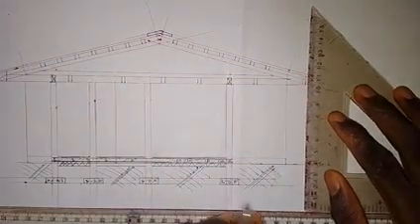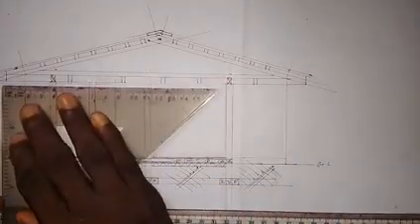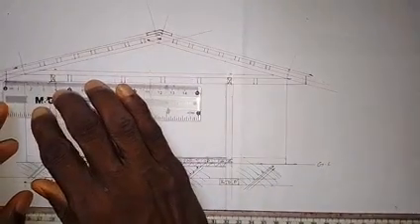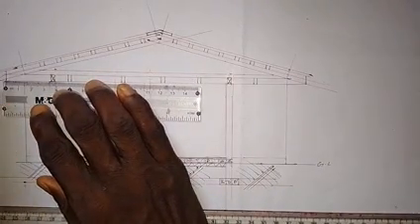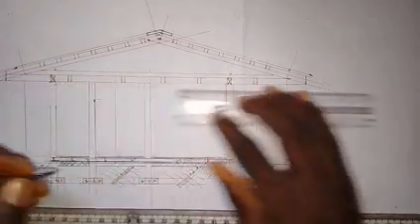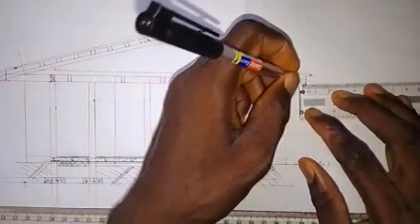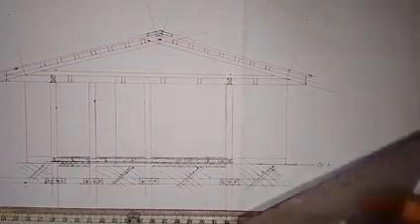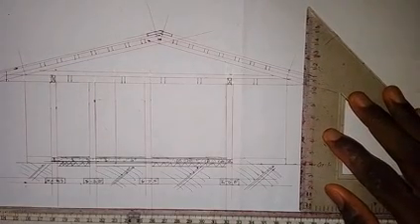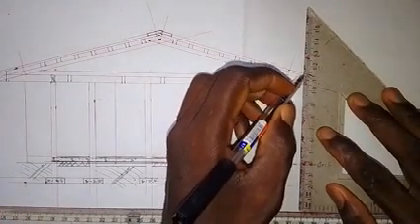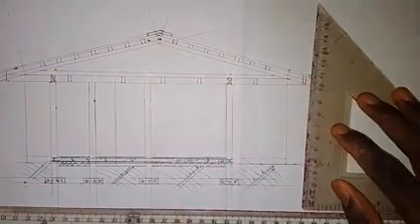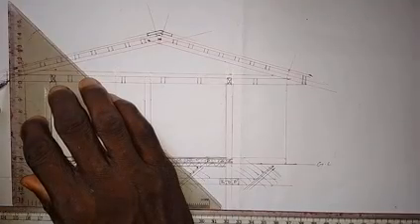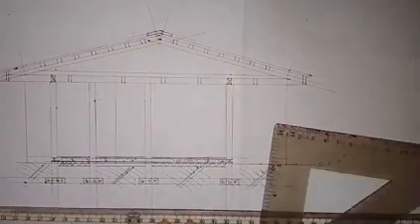So then for the facial board, we need to also take a measurement of the facial board. So I'll just take 2 millimeters for the facial board here. I'm coming here from this point, I will take 2 millimeters for the facial board. So I'm going to draw a vertical line at this point. So here I will draw a vertical line. So that is from here to here. So I will also come to this end and draw a vertical line from here to here. So that is for the facial board. Then I need to terminate the roofing material.